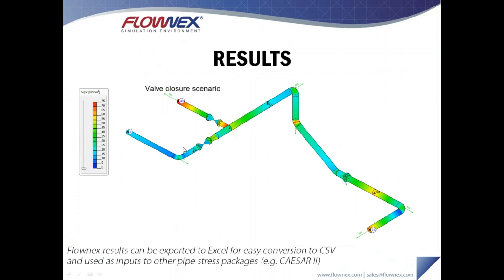Alright, so just to recap, the RAW simulation, all of that geometry can be exported into a file that can be read by Flownex. This file is then imported by Flownex. We specify some boundary conditions and configure our dynamic event that we would like to simulate. In this case, say this water hammer scenario. We then solve the network in Flownex. This information is written to a CSV file, which then is read by RAW and can then be used in its structural calculations. We can then view those results either as displacements or stresses, for example, and then do any further analysis on the system that we would like.